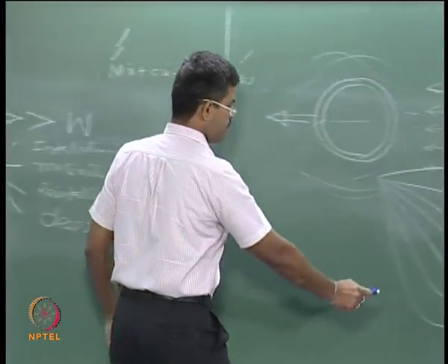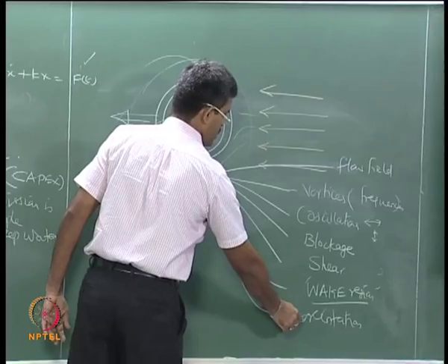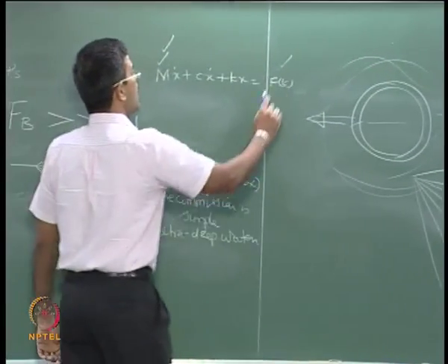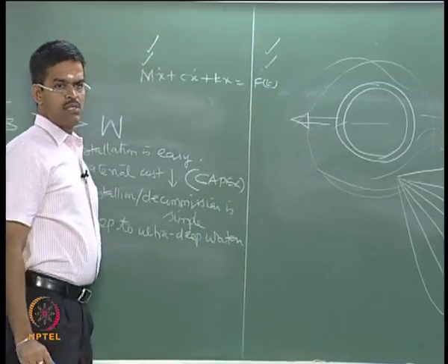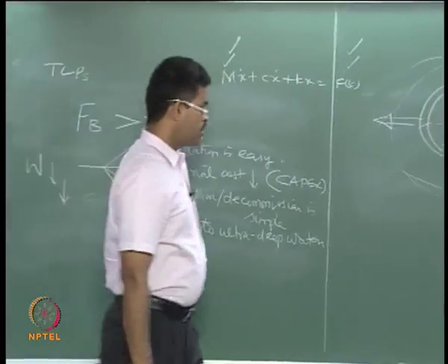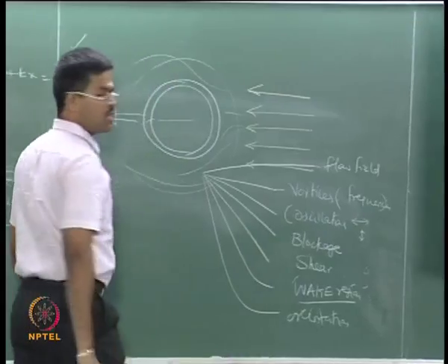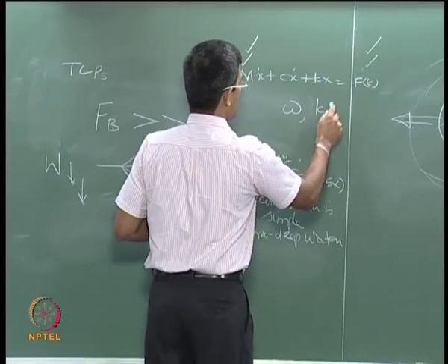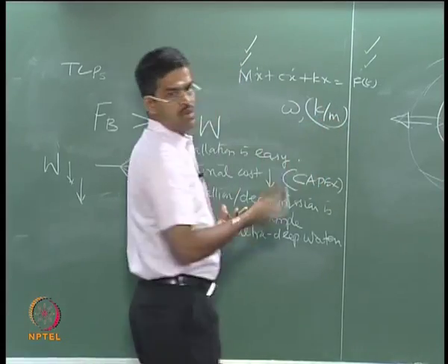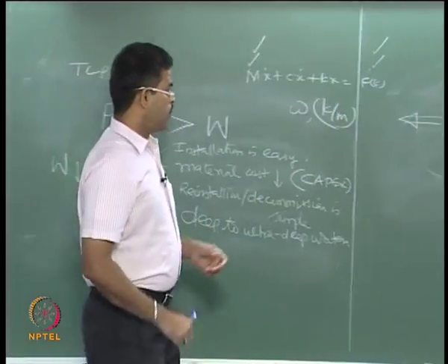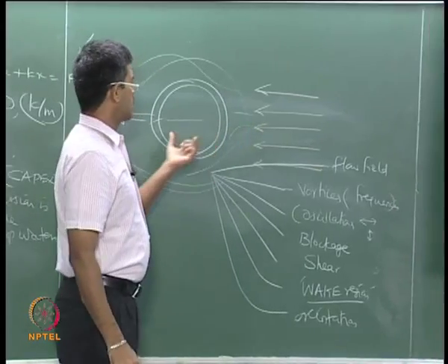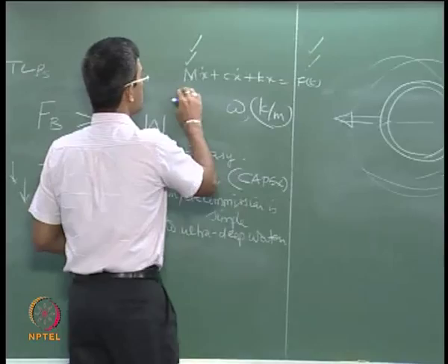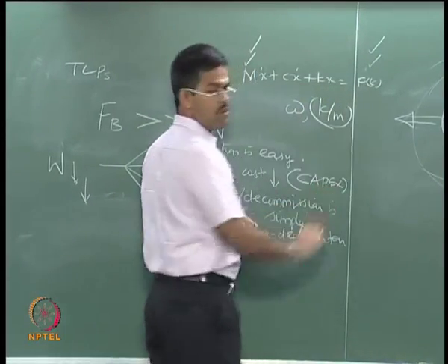The orientation of the member can create vibrations along and across, which will again produce forces in a 2-dimensional state. Vortex induced frequencies will cause secondary vibration, which will affect omega, which is again a function of k and m of the whole system. So fluid flow with an interference to a structural member, which we call fluid structure interaction, can influence many parameters in your equations of motion.